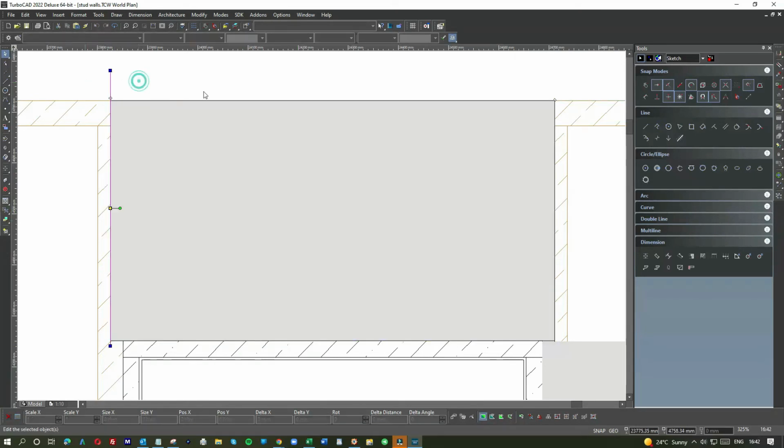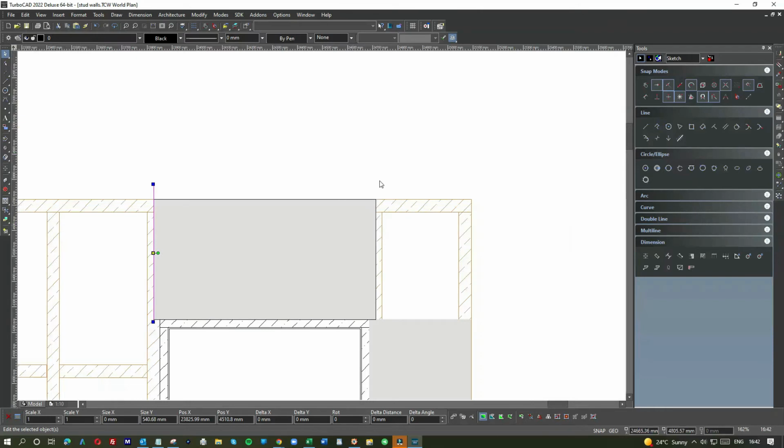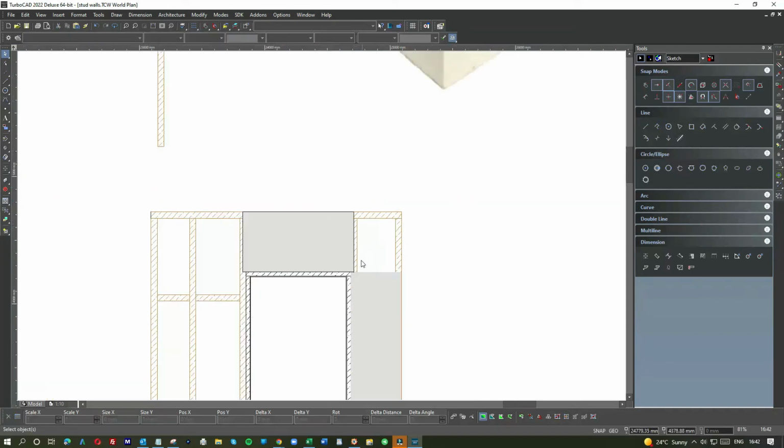So you see what happens is when the board covers the stud, it goes halfway. You can't have the board halfway on the stud, so it's covering all of the top plate, all of the header plate above the door, and half the two uprights. So now you've got timber for these three elements.